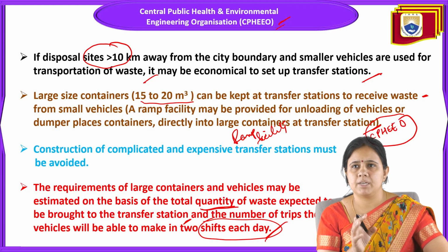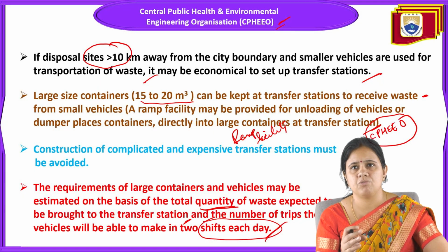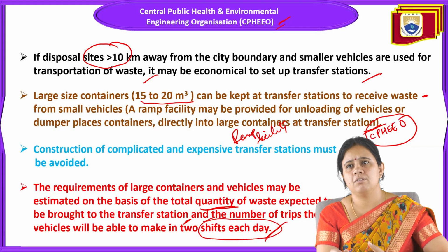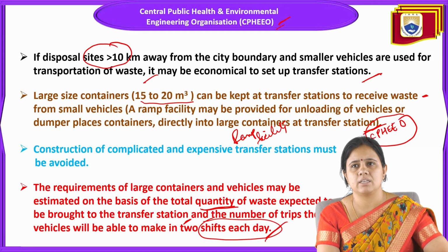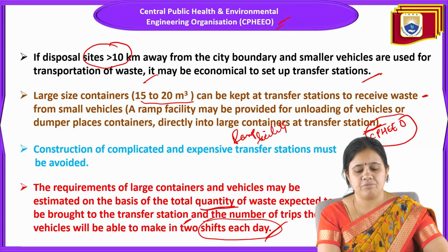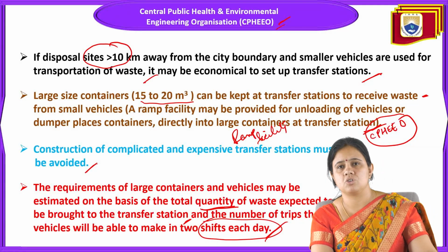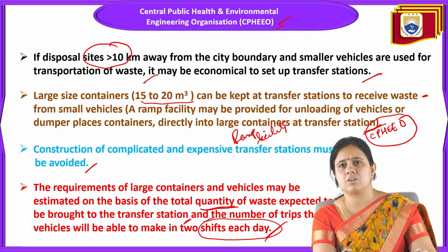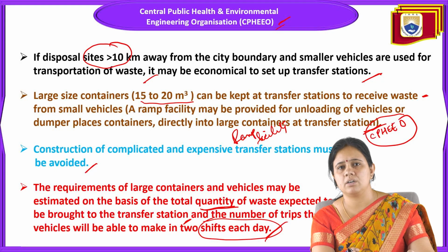Large size containers can be kept at the transfer station to receive waste from smaller vehicles, and a ramp should be provided for the unloading of vehicles or dumper placer containers directly into large containers at the transfer station. Construction of a complicated and expensive transfer station should be avoided. Obviously, if it is very complicated or expensive, then it will not be efficient or cost effective.